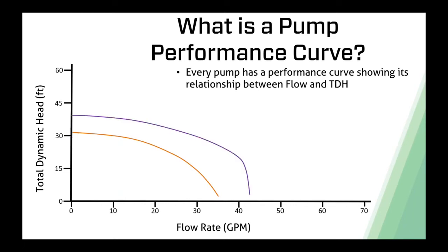So pump curves can look different ways. Sometimes they're smooth, like the first one that was shown. Sometimes they have a little bend and it may drop vertically down. That little bend there is what we call the knee of the curve. Not all curves have that. It's kind of a special case.